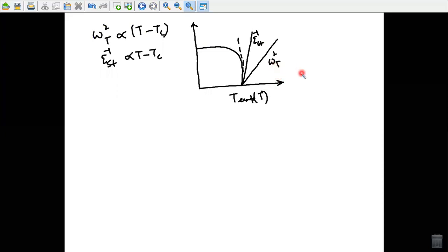On account of their large dielectric constants above the Curie point, ferroelectric materials, in particular ferroelectric ceramics, are of great technological importance as dielectrics in capacitors. Below the Curie point, the ferroelectric ceramics have a large piezoelectric constant. Ceramics with suitable Curie points are utilized as piezoelectric actuators.